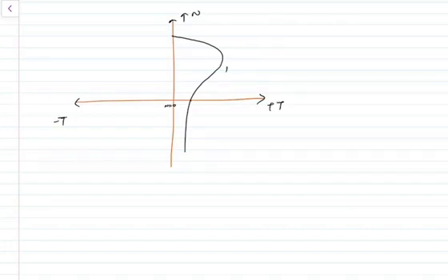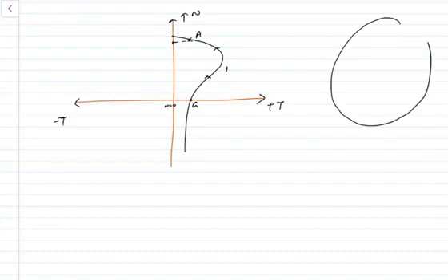So whenever you are starting your motor, it will start from some point, G. It will travel like this. Let us assume it stabilizes at some point, let us take this point as A. That means it will continue to run corresponding to the speed. So in order to apply the plugging, what we have to do, we have to change the polarity of any two phases. Because we know if you are taking your motor, let us take it as this is R phase, this is Y phase and this is B phase. So RYB is given.